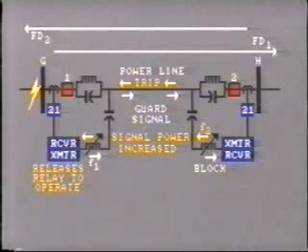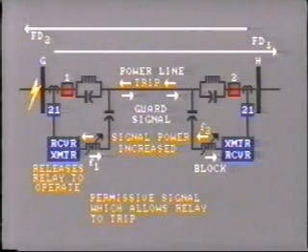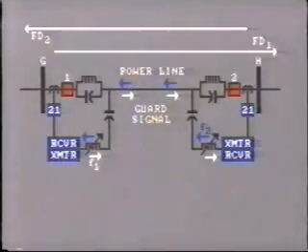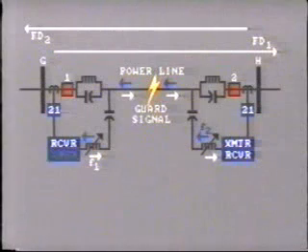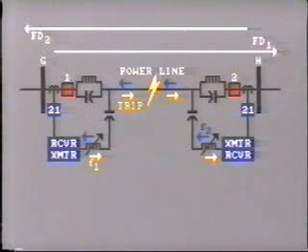In effect, the transmitted signal is applied as a permissive, which allows the relay to trip when the fault is within the protected zone. Now, let's look at the case of an internal fault, let's say halfway along the line. At station G, the fault detector detects the fault and keys the transmitter to change frequency to the unblocked mode, so giving permission to the relay at station H to operate.